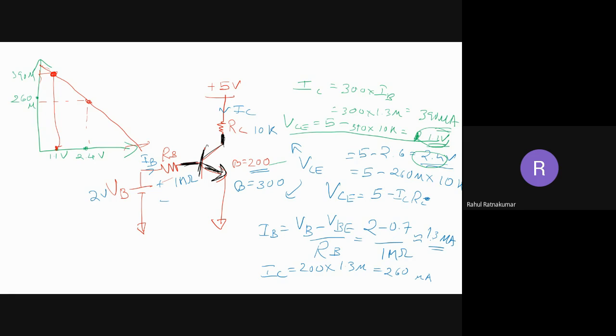What should I do to make the transistor come back to the older position internally, without any external help? So this is undesirable. Sometimes if the beta reduces, this will be the new operating point. This is also an undesirable operating point with less IC and very high VC. So here also you're operating near the cutoff region. So it's not good. Okay, so we'll discuss the concept of feedback.